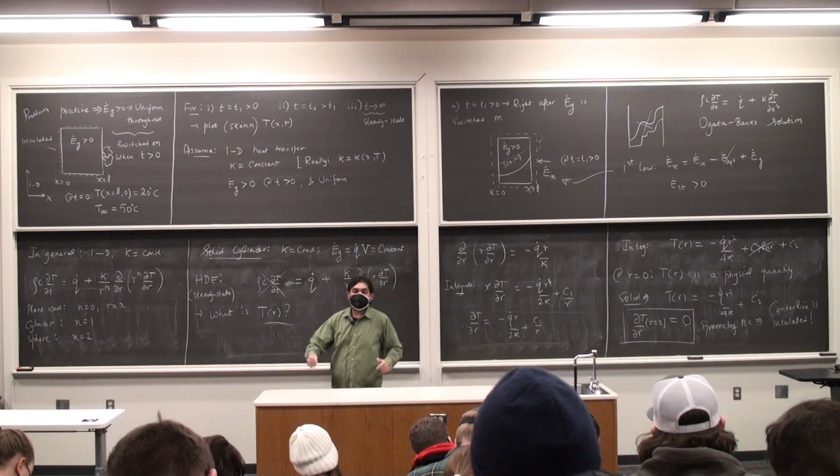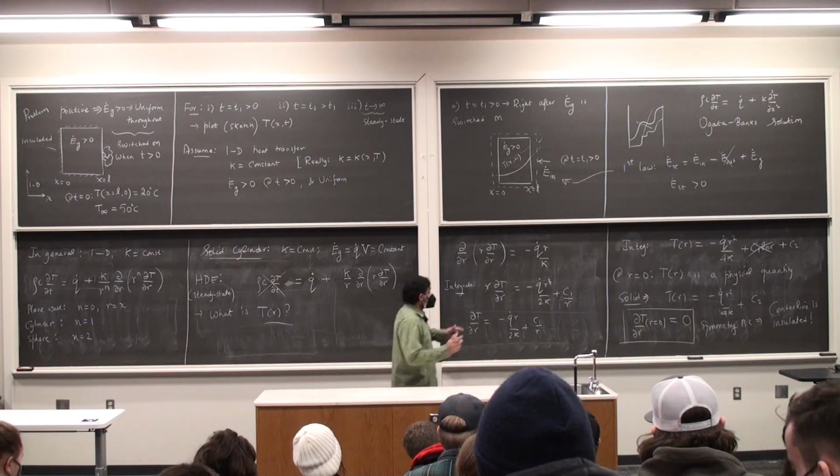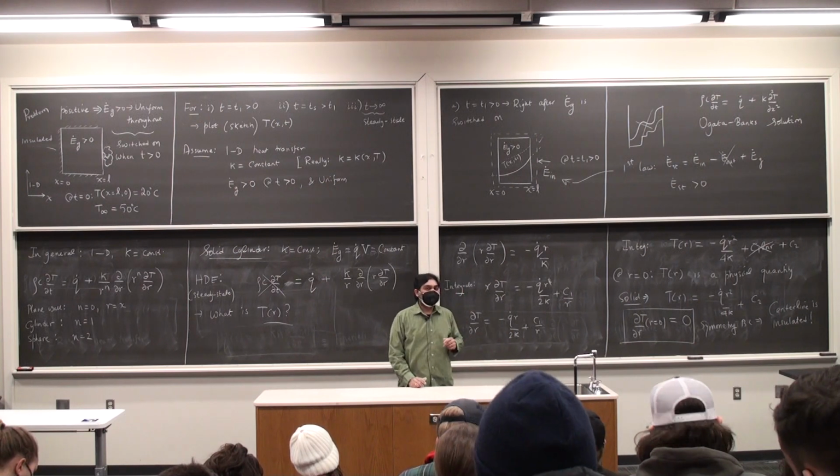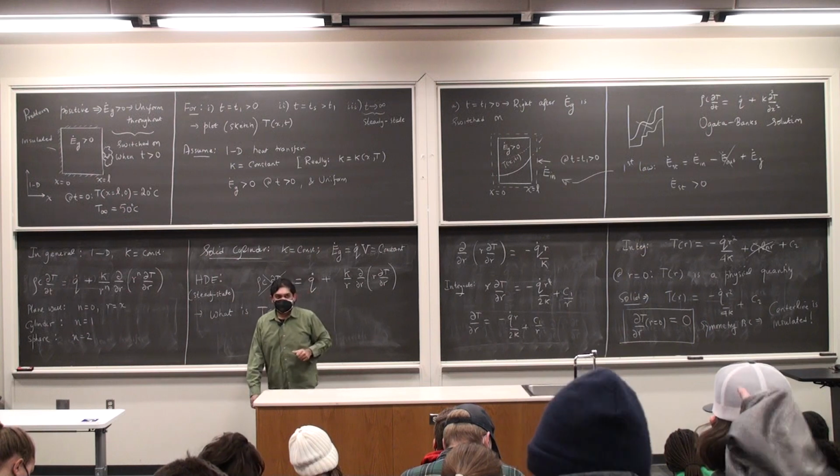Yes, question. And that's because our heat transfer is in the radial direction, not the length. Absolutely, because if it was in length, the heat diffusion equation would have changed. That would have become a two-dimensional one. So we can't solve it using this technique. All right, thank you.